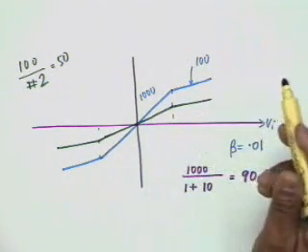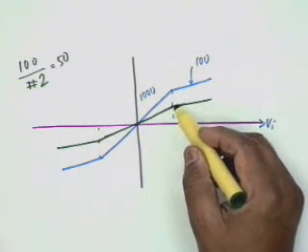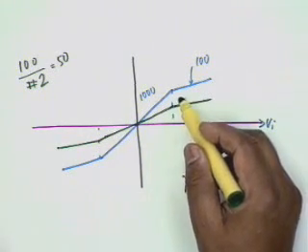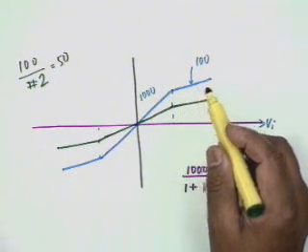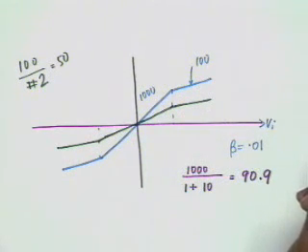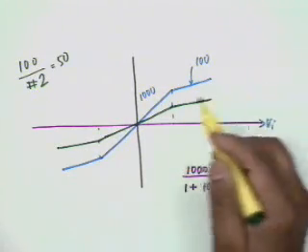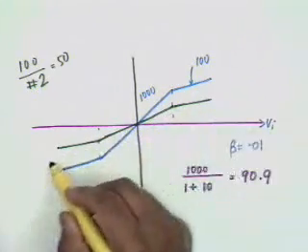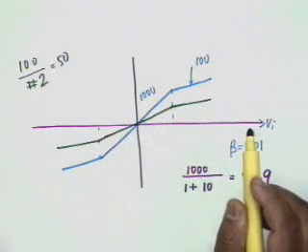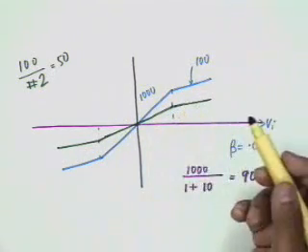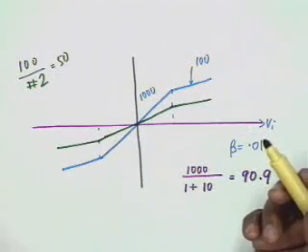In other words, the transitions or the discontinuities are smoothed out by negative feedback. And if you apply sufficient feedback and the gain was sufficiently large, you can make this curve almost a straight line. These kinks are reduced and therefore there is a reduction in nonlinear distortion. This is a qualitative picture. Now let us look at it quantitatively. What is the price that you pay? The gain.